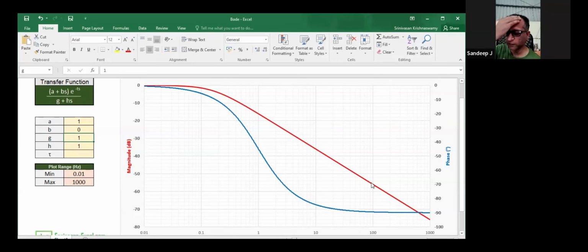The point I'm asking about is not the filter perspective. I'm talking about a conventional Fourier perspective. For example, if you have a system which is asymmetric, you're expected to have a dominant third harmonic, which is bad sounding, at least in terms of sound, and on the multiples of the odd order harmonics, if they take the dominance, which happens in amplifiers and preamps. Why that happens is that you start operating your amplifiers closer to the saturation region of your amplifier.